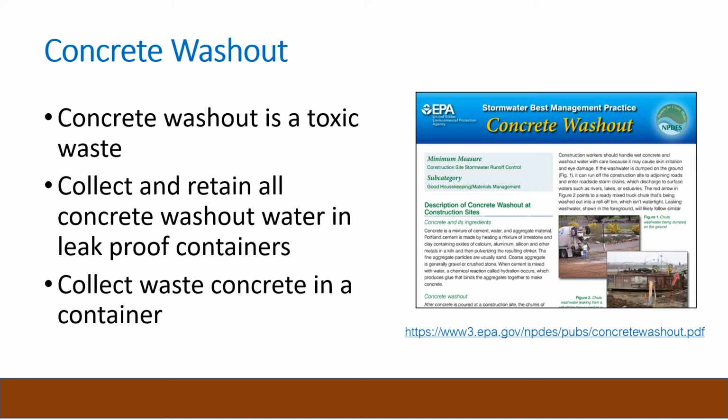Concrete washout is a toxic waste that has a high pH. It is important to collect and retain all concrete washout water in designated leak-proof containers. Shown on the right is a handout that provides guidance from EPA. Concrete waste should also be contained and disposed of.